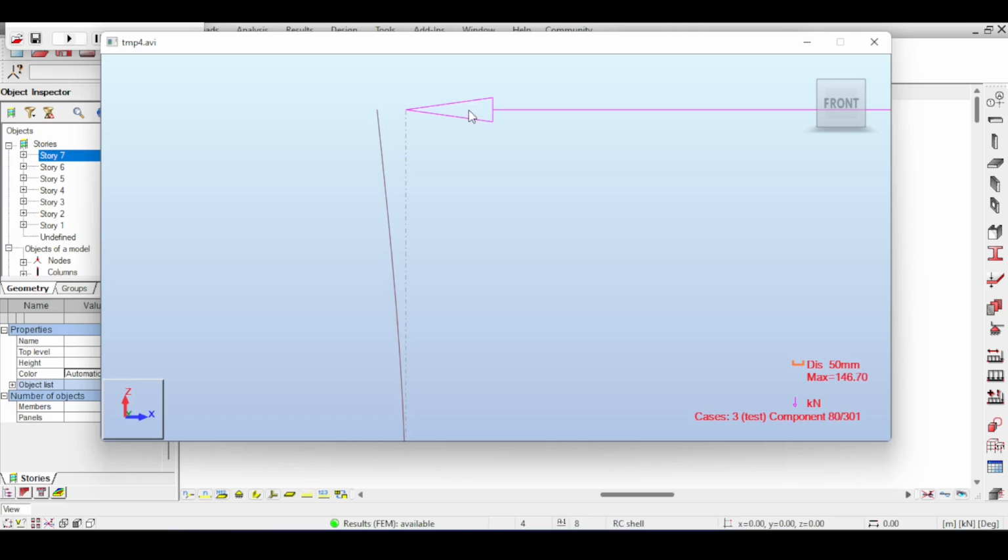Take a look when the force dies right now. When the force dies, which will happen in a moment, you can see that the structure vibrates back and forth, but with each passing vibration, the vibration dies down. If you look at the mouse position here, the vibration is now not reaching the mouse position. If I go back with it, you can see that in the next cycle the vibration will not reach the mouse position, and so on. So what ends up happening is the vibration dies down because of damping. And that's exactly what I wanted to see. So now we have applied damping to our little column structure.